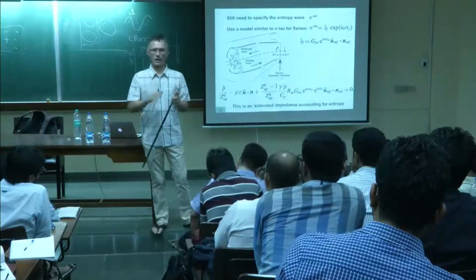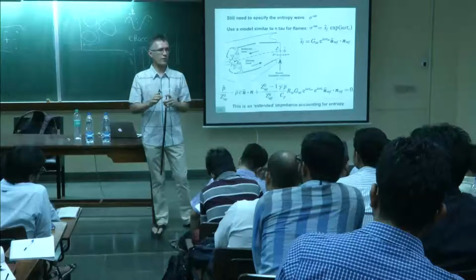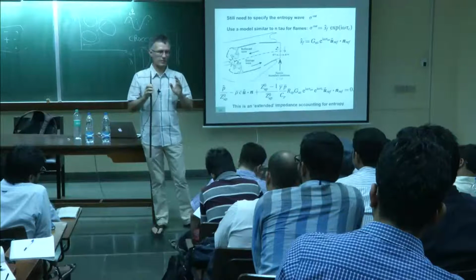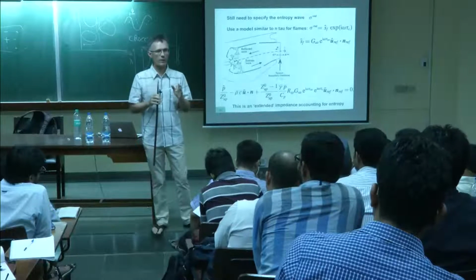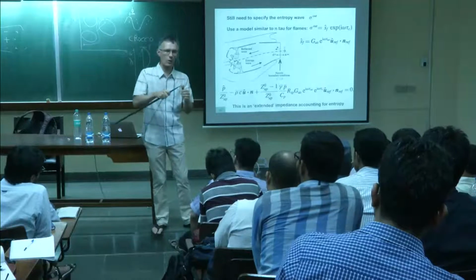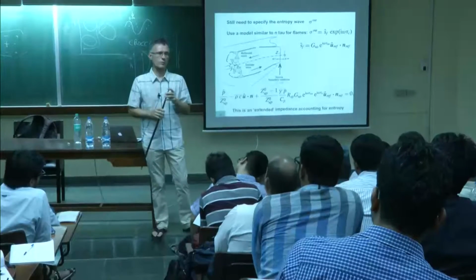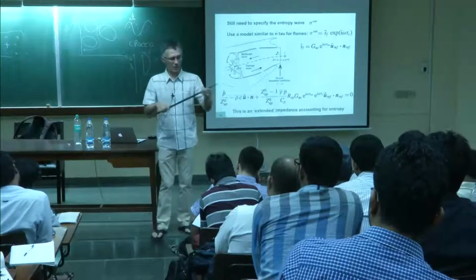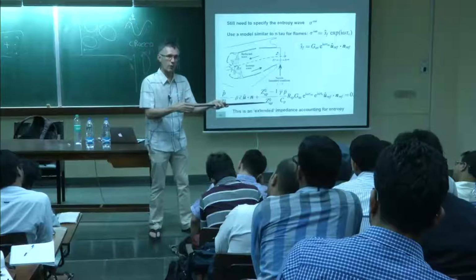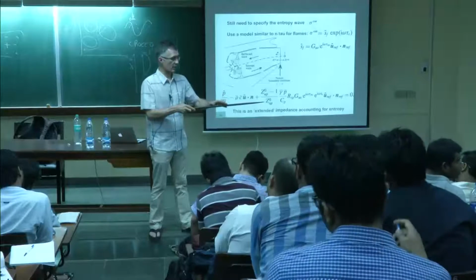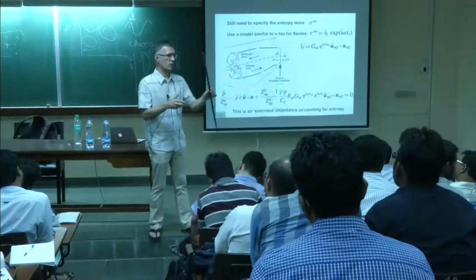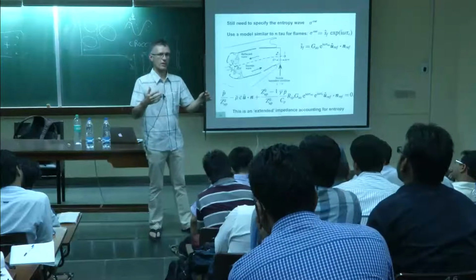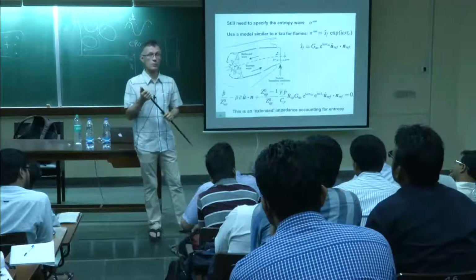So for rocket motors, I think today we have LES, and we have very few acoustic models because transverse modes are a real difficulty. We don't know how to write the transfer function because here we have a system where basically we say, if I fluctuate the flow rate, I fluctuate the heat release. But now if the instability is transverse, all this disappears. And so rocket engines are much more difficult, in other words.